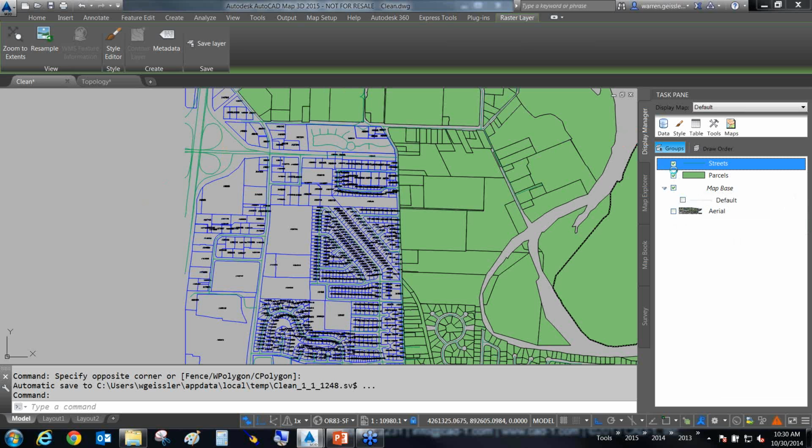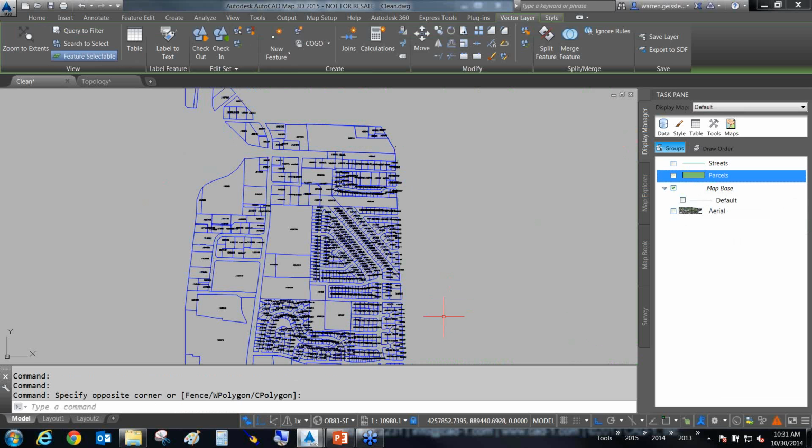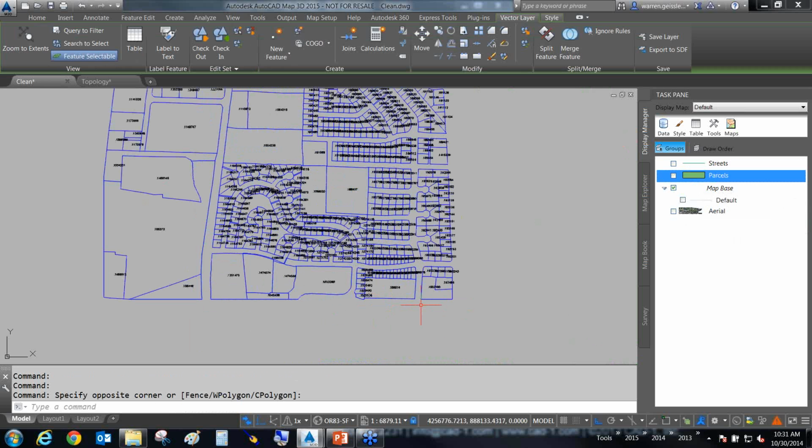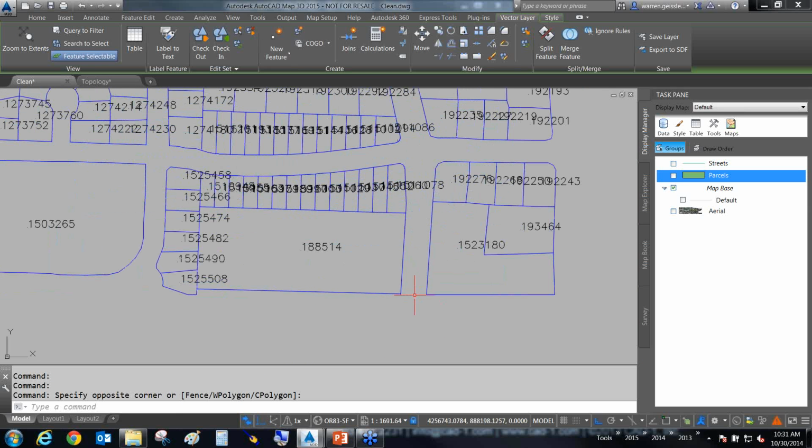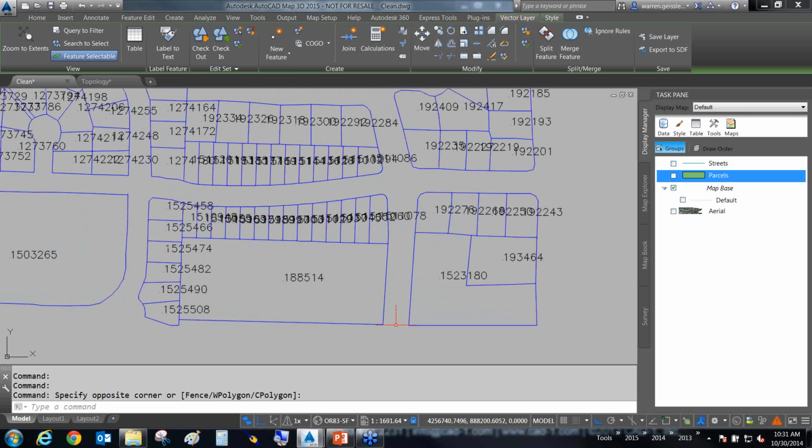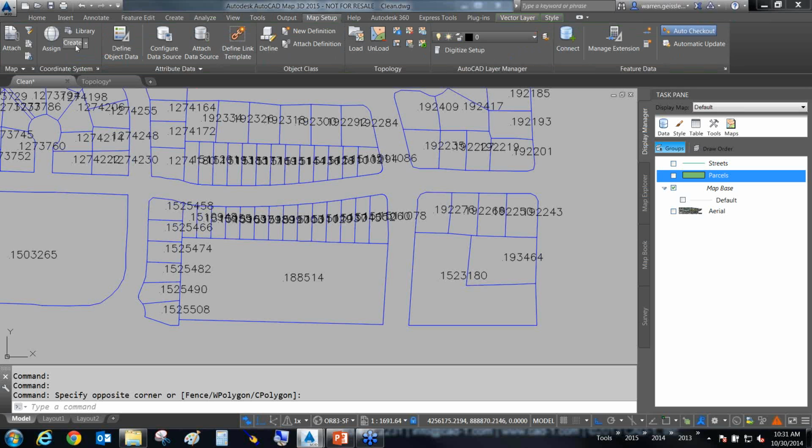All right. Scott asks, I'd be curious to hear about transformations from Esri Grid to CAD and survey ground on modified state plane. Usually a scale factor around a base point is provided from the surveyor. Right, and that gets back to what we were talking about earlier. When we're talking grid to ground, it's a very easy system to work around depending on how the grid to ground was affected inside the drawing. If you are doing it properly, you build yourself your own custom coordinate system using that scale factor, by using this little create button that I'm showing you right up here. Use the create button and build a custom coordinate system that takes that scale factor into consideration.